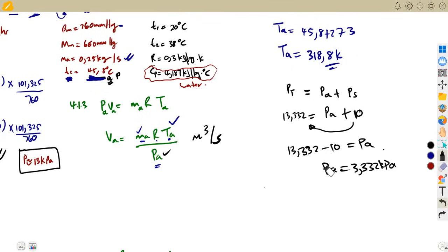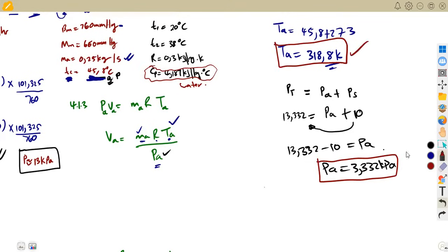We can change that mass to kilograms per minute. All right. So let us just convert at once, because we just want to insert our values at once. This one is fine in Kelvin, in kilopascal, but this one is not going to give us the volume in cubic meters per minute. It's going to give us our volume in cubic meters per second. Yes, you can convert on the final answer, or you can just convert the mass direct. We are given the mass of air as 0.25 kilogram per second, means 1 second.